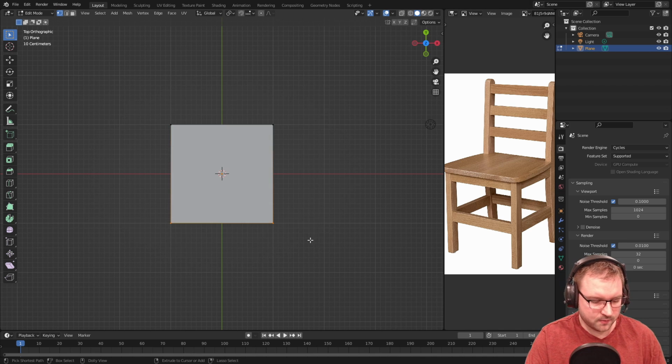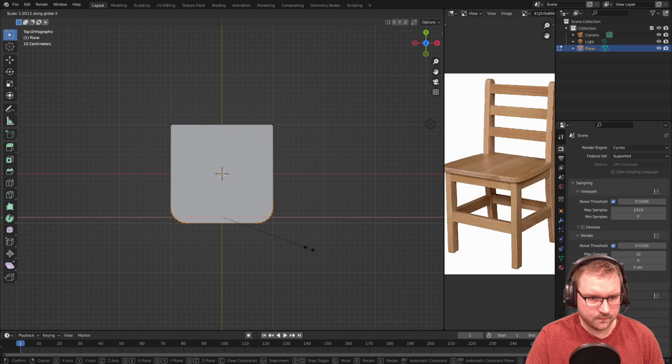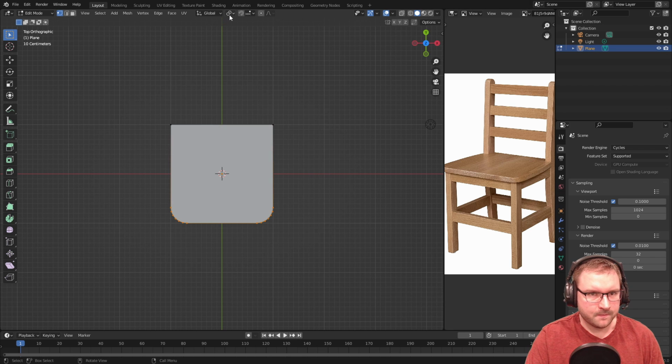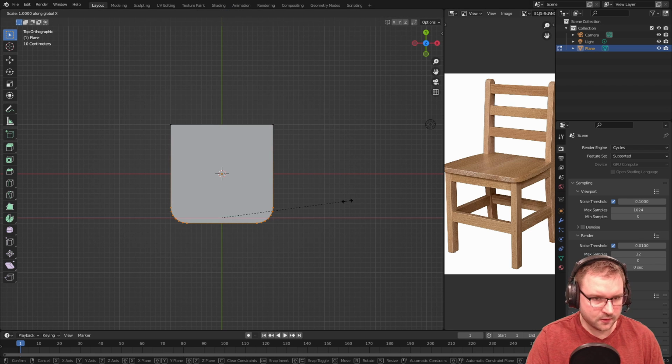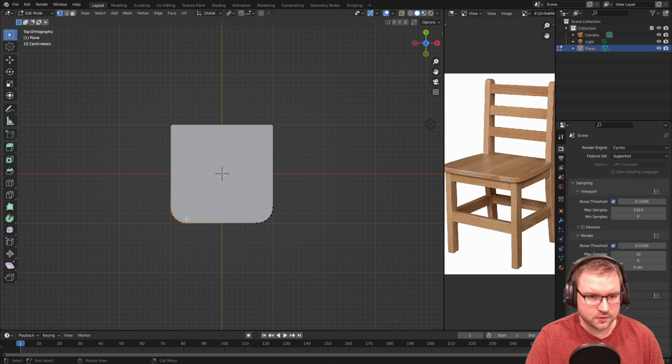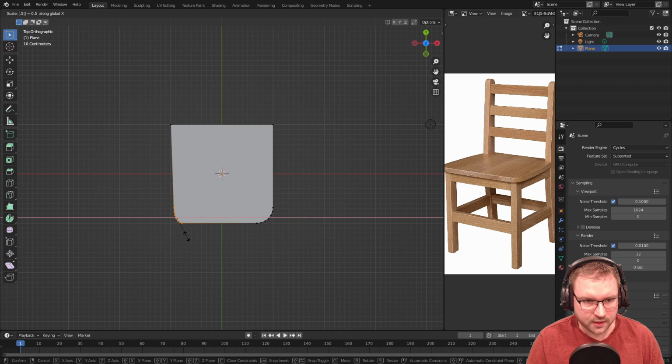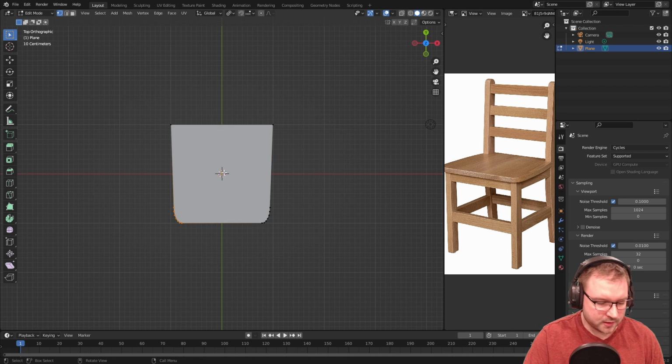We'll bevel the fronts. I'm going to make it a little unique here. So bevel the fronts like this. And I might scale them in the X a little bit. Yeah, scale X. I might have to do these individual. Let's see. Individual origins, scale X. Now to scale these like this. I'm going to try to use a number to keep these consistent. So I'll do scale X and I'll try like 0.5. Okay, I think I like that. Scale X, 0.5.